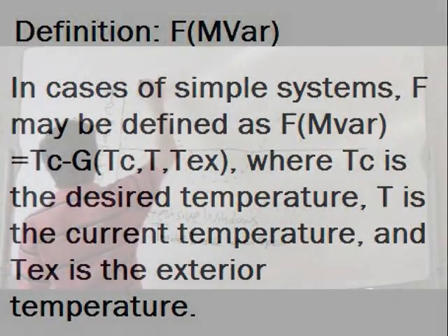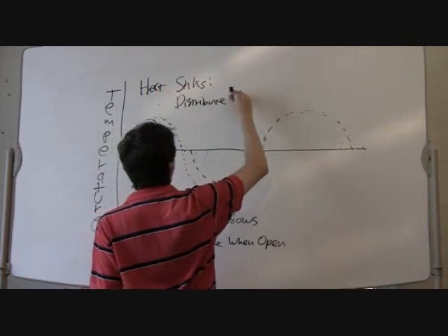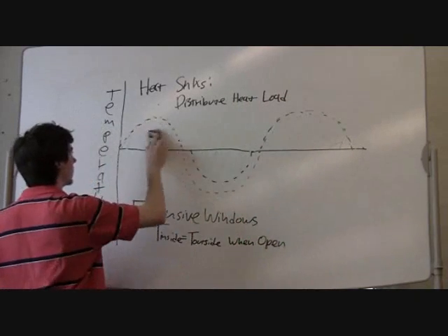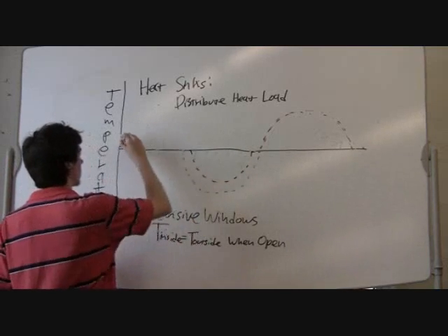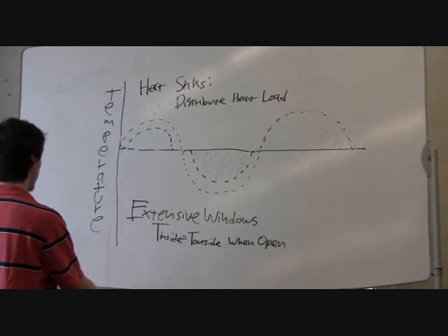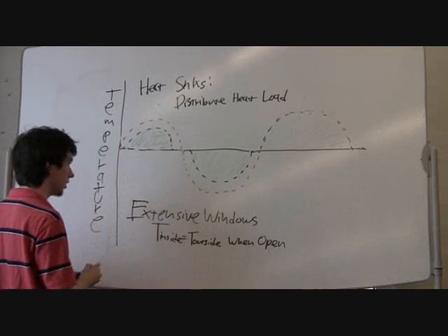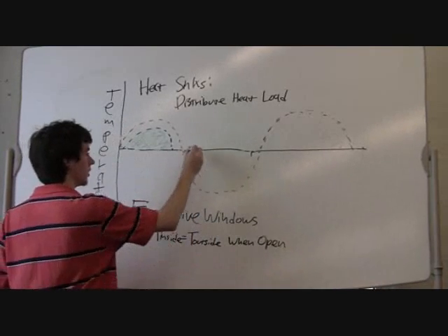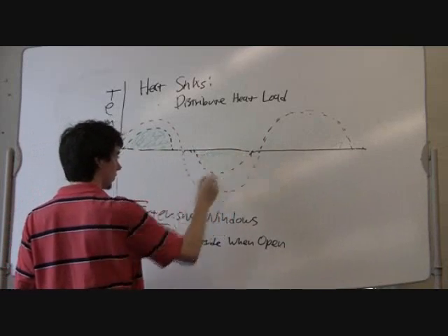For instance, the performance of heat sinks depends not only on the current temperature, but on the previous temperature throughout various points in the day. Other cooling systems can depend on additional variables. For instance, the effectiveness of shading depends on how much sunlight the greenhouse is receiving at the time, which, while linked to temperature, is not the same variable. The effectiveness of other systems, such as evaporative cooling, can depend on technical factors, periods throughout the day, or other time-based influences. Combining all of these factors into one final function, f, is a task of non-trivial difficulty that becomes increasingly complicated the more design features are added.